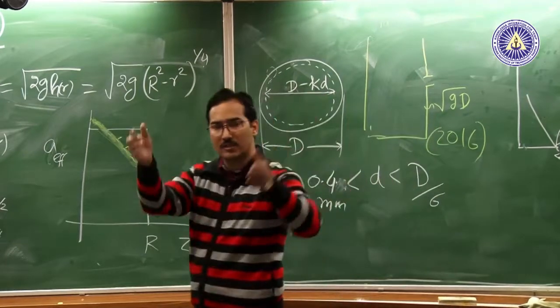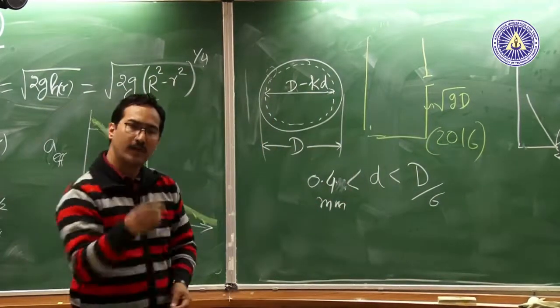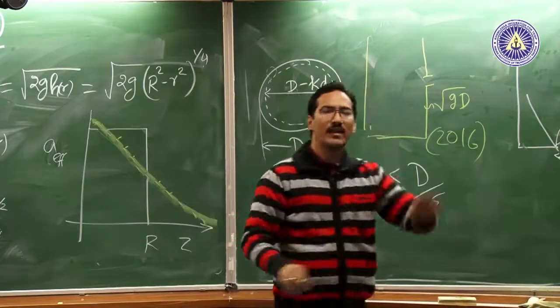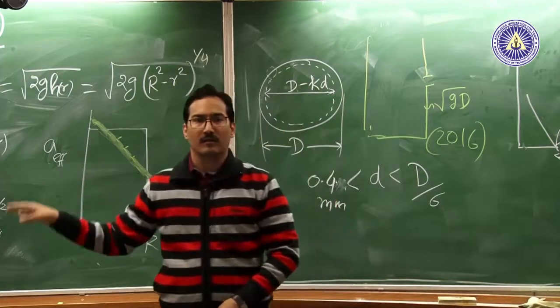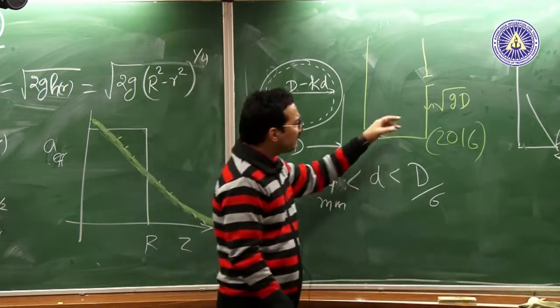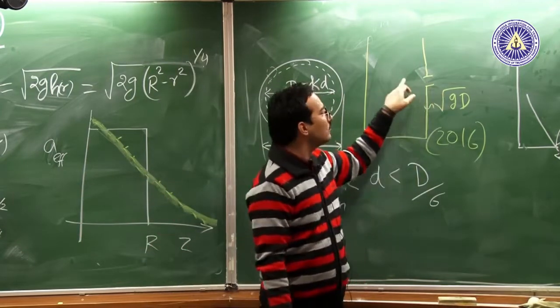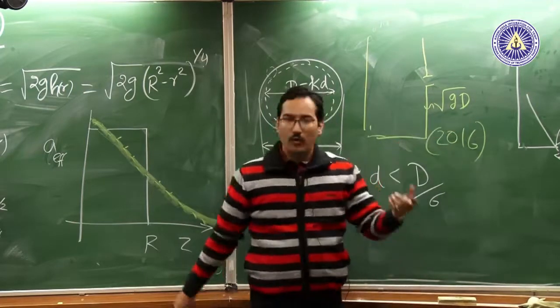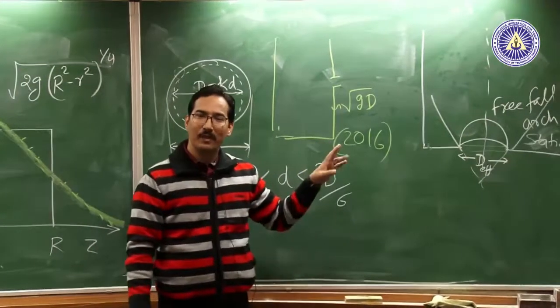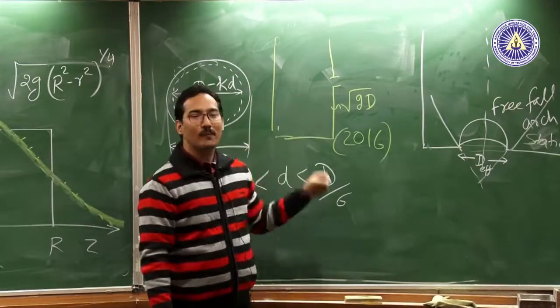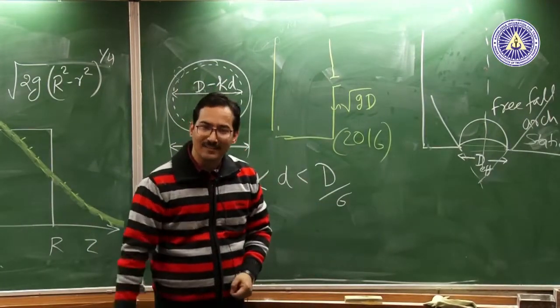If you have a hopper which is tilting at an angle, or your material is different, you add correction factors based on that, and that is why it has been surviving for so long. And in this case, you see that the velocity scale again goes the same way. The only thing that changes is your constant of proportionality. The only interesting thing being that your flow rate also depends on the container thickness.